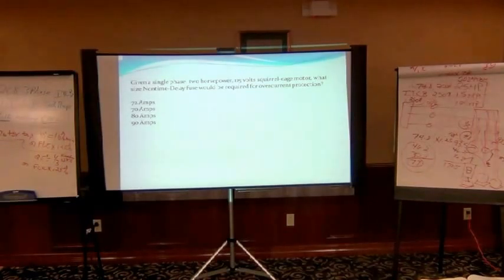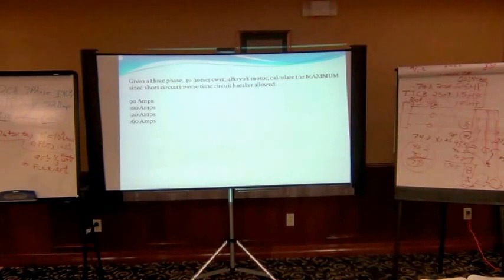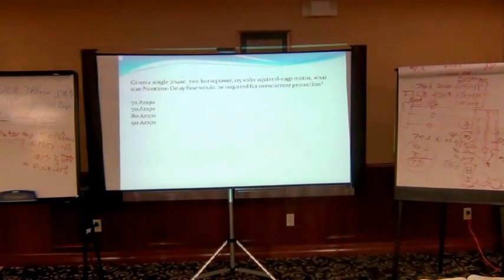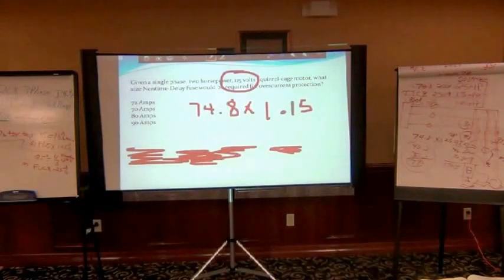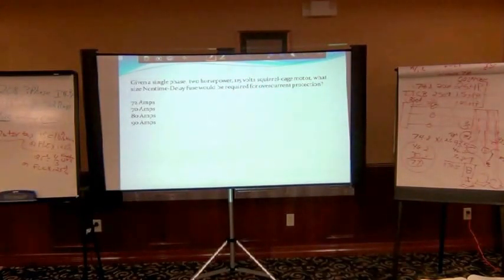24. So 24 then is my FLA value, from page 337, is it? Yeah. For single phase horsepower? Single phase 2 horsepower? Yeah, 2 horsepower.